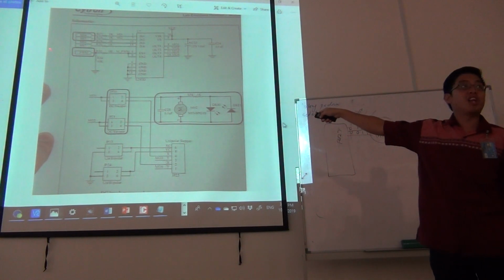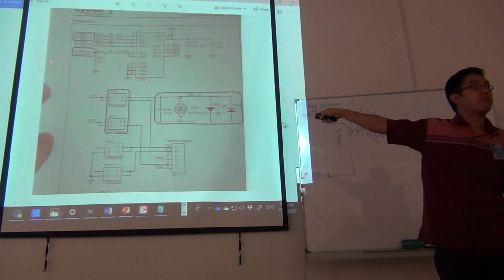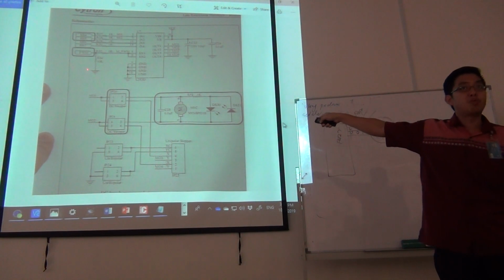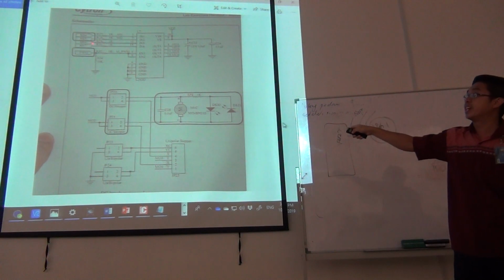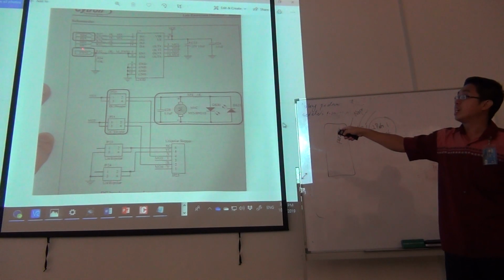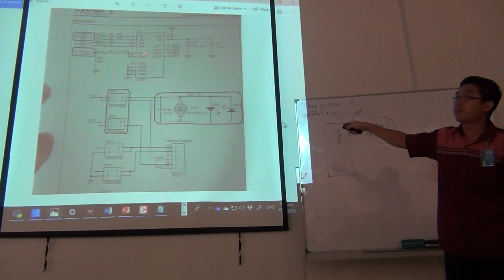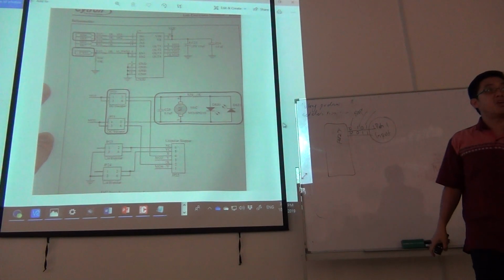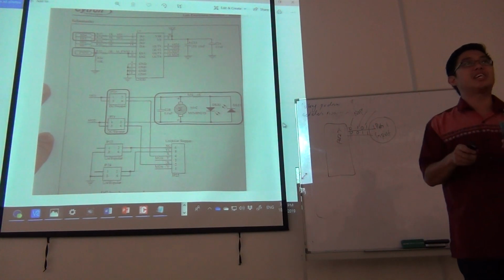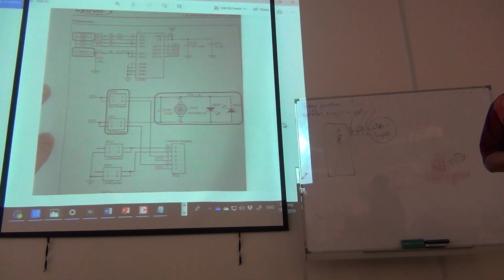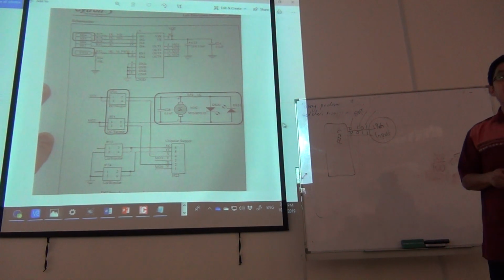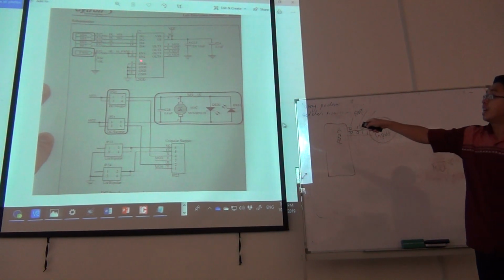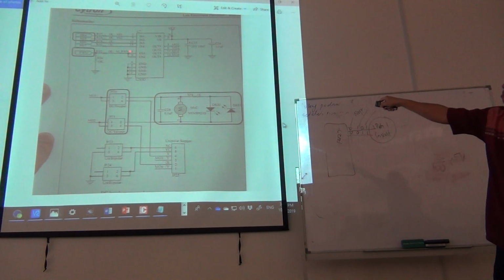Now let's look at this point. This point they call PWM. PWM is coming from your PIC pin CCP1 or CCP2, correct? So now let's look at over here. PWM is going to be over here for the enable 1 and enable 2 pins. From the L293D just now, enable must be connected to the PWM pins, which are the CCP pins. Must be connected. Alright?